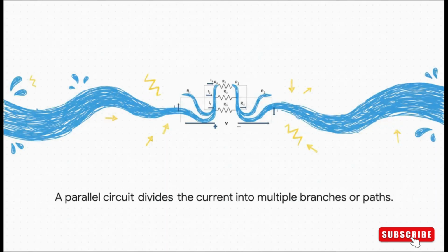This diagram shows it perfectly. See how the main current, I, comes along and then hits a fork in the road. A portion of it goes down the R1 path, another chunk goes through R2, and the rest goes through R3. It's like a river splitting into 3 smaller streams. That's why we call parallel circuits current dividers.